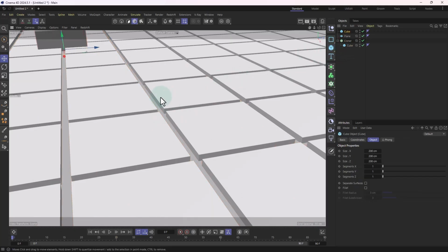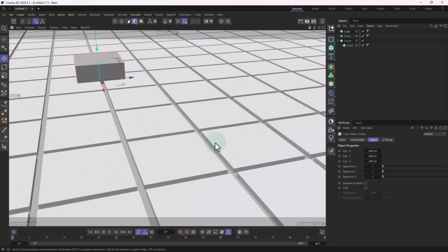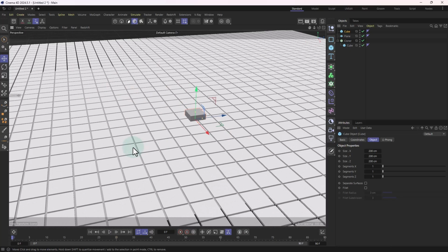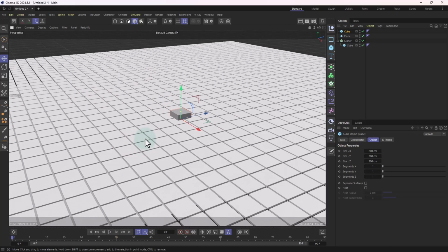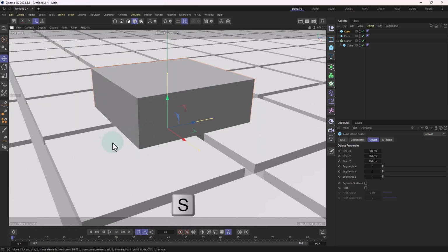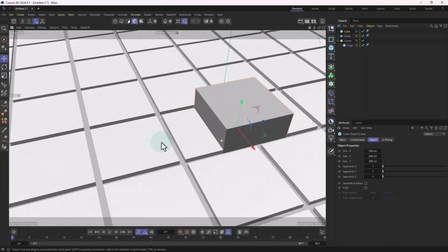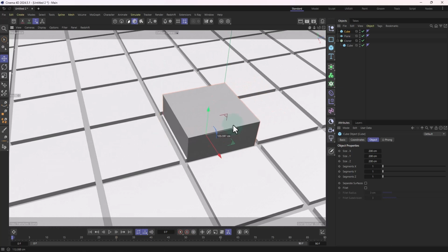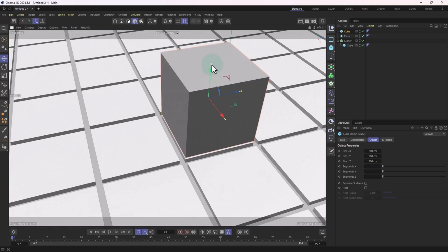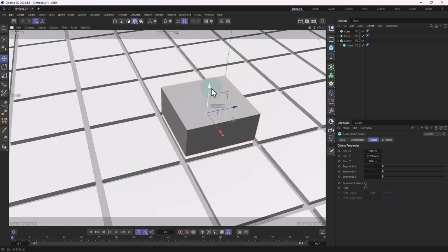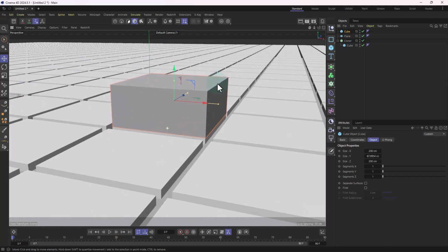If you create a cube or you put anything in an object and it's very far away from you, you want to just go directly to the primitive that you have, you just hit the keyboard shortcut S, and to go close to the object that you want to snap to, go closer actually. So you bring it like so in the middle. The height is too much, we bring it down. Yes, this is what we have.